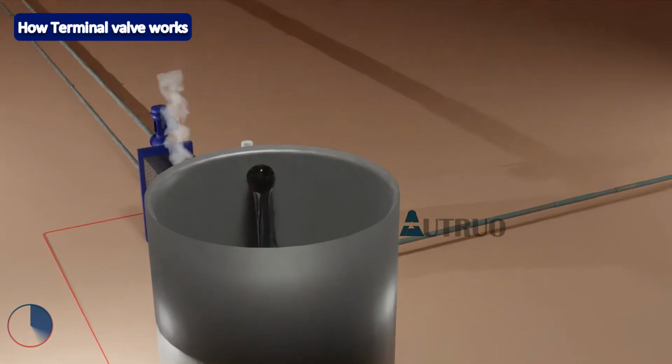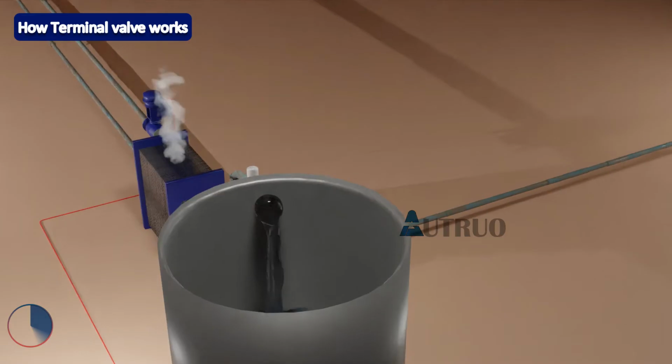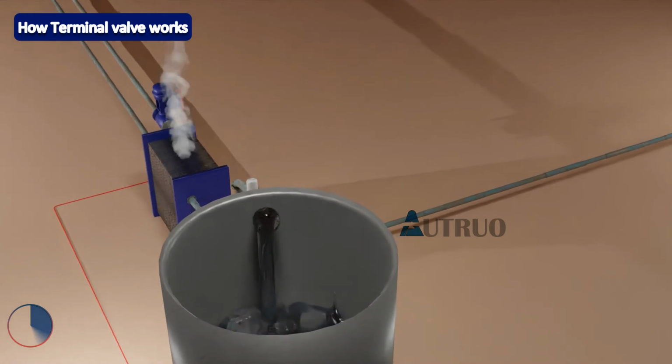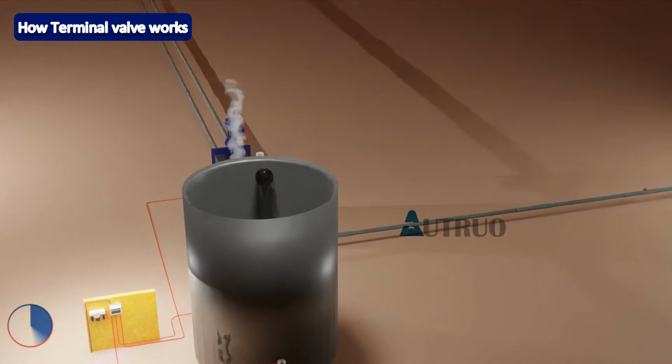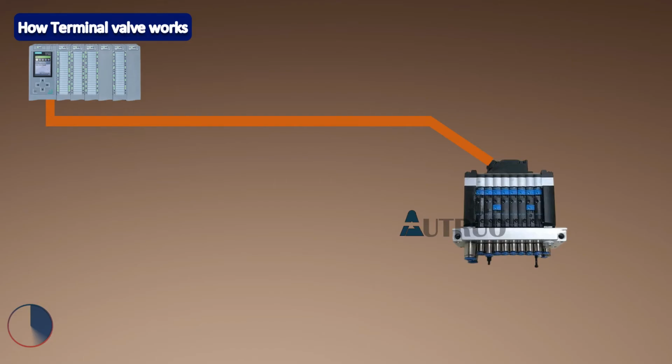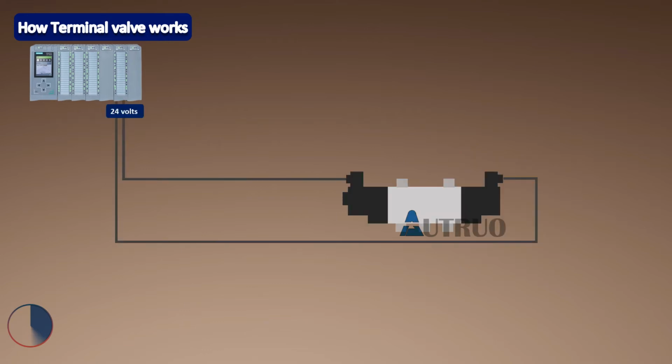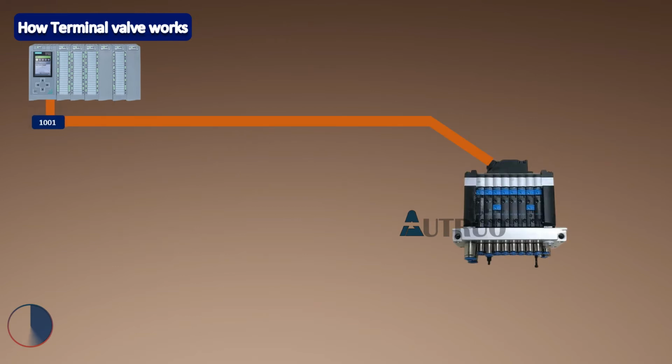The valve is powered up by a single source of 24 volts supply at the input. This voltage source is what will be used to actuate the valves on each channel. The output channels are actuated electronically. Which means instead of sending 24 volt supply to the field devices via the PLC I/O card, the PLC will instead communicate to the valves through digital means. The most common types are Profibus and ASI communication systems.